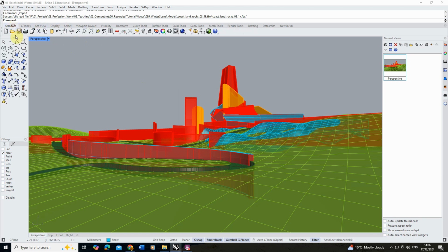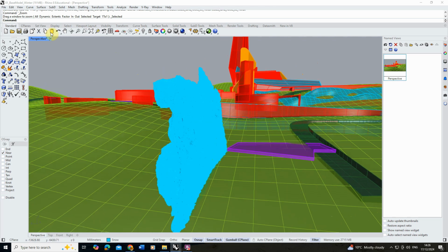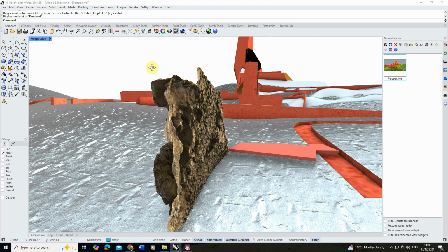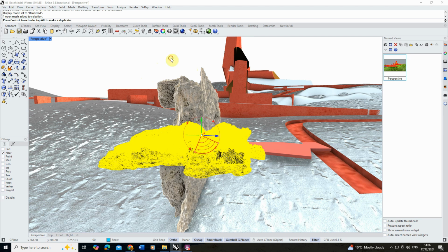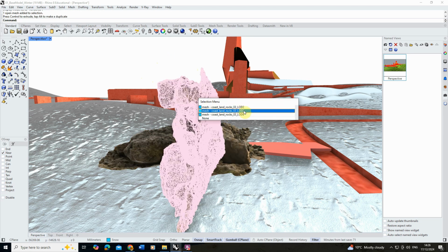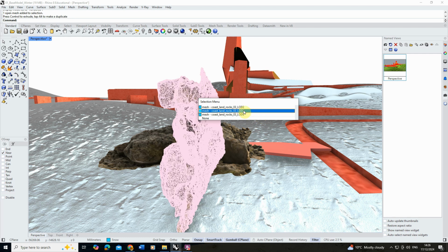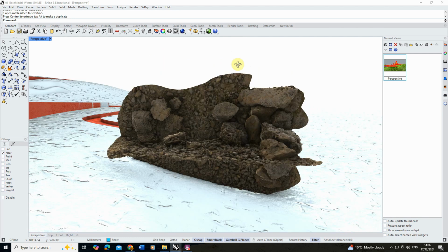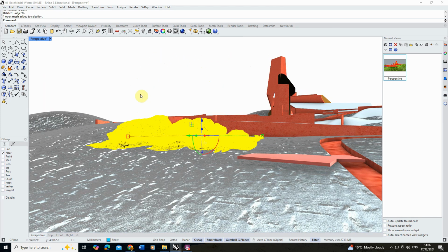Once that's in, I'm just going to zoom selected to locate that object, which is usually at the 0,0 point of your file. And then we're going to rotate it around so we can accurately see it. Now usually this is easiest done in the rendered view, so we can actually see which way up the object is. You might find that you get a few of these in here, and the reason for this is all of them come in a different level of detail, which means the number of polygons in the scene will be different. LOD 0 is the highest number, down to LOD 3, which is the smallest there. So depending on the resolution you need for your scene, you might want to choose a different resolution. I'm just going to delete all of these and I'm going to work with this LOD1 object here.